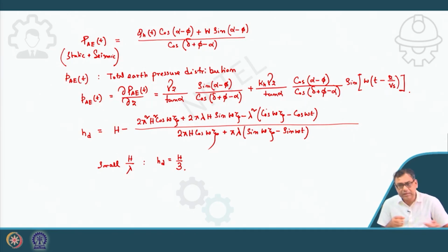Here you can see in the simplified form the time effect has been incorporated. In the pseudostatic approach it is simpler, with no time effect, but this is also a simple approach where more time effect is incorporated. If you want to do the real dynamic analysis, then you have to use a numerical tool with an advanced constitutive model suitable for dynamic loading.